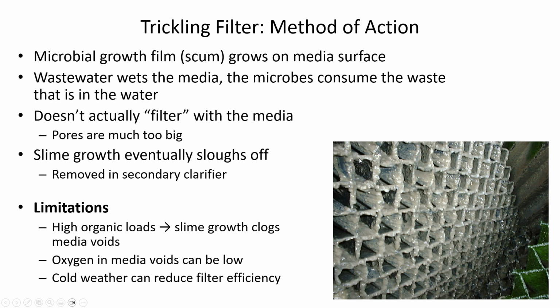And this is especially vulnerable to cold weather because air doesn't hold temperature as quickly, or as long as water. And so an aeration basin will maintain, even in really freezing cold temperatures, roughly the same temperature as the water that came into the treatment plant, like mid-50s, 40s or so. But when you have a really thin layer of water, it loses its heat more quickly. And that's what we have here in trickling filters, very thin layers of water that are more susceptible to cold weather.